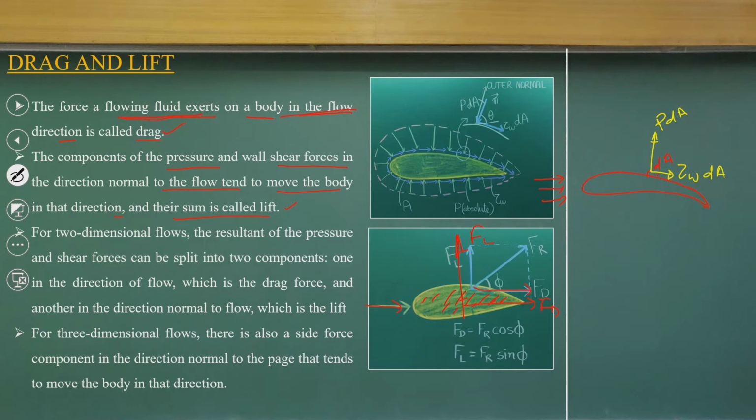And I have the normal component, and I can look at that it is making a theta degree angle with the horizontal direction, the flow direction. As you discussed in the boundary layers, there will be a generation of boundary layers, the flow separations and boundary layer thickness, which generate the wall stress variations.